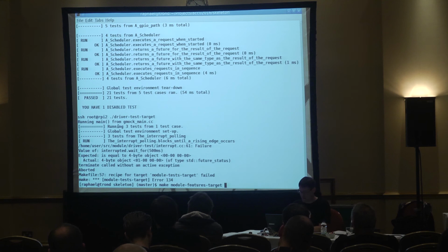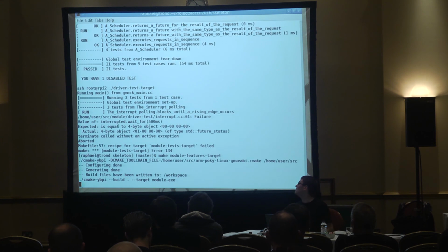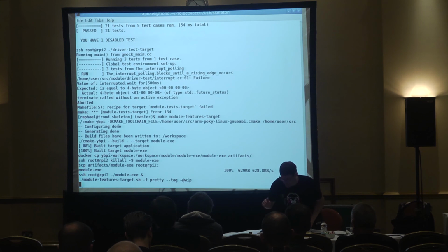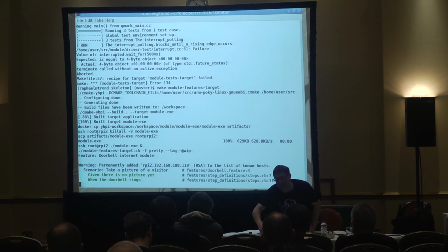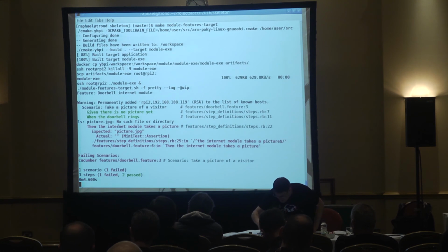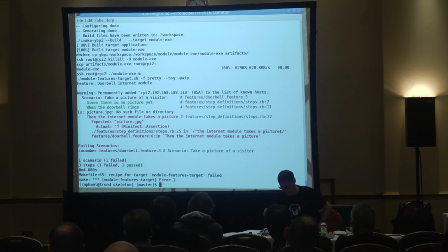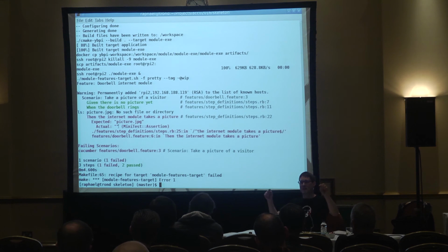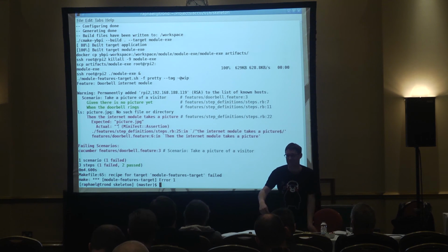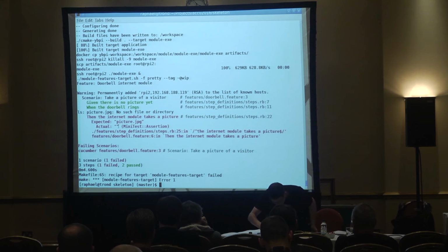Also for the acceptance tests, I have some tests that run against the... For that I also need a little bit of special configuration, because what you often would do is try from the outside. For example, you have some GPIO expanders or whatever that your test can use to trigger your hardware. What I now do is I'm just abusing the Raspberry Pi to itself being the external component that drives it. For that I need to put in a few cables.